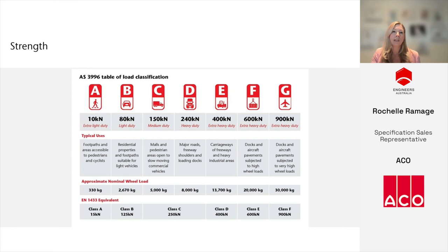The only standard written specifically for grated trench bodies and grates is the internationally recognised EN 1433. This standard includes different grate widths and different channel sizes. It specifies test methods with loads up to 900 kilonewton for both the grate and channel body. The test accounts for both serviceability and ultimate loading. It's an important standard, particularly where vehicles are involved.